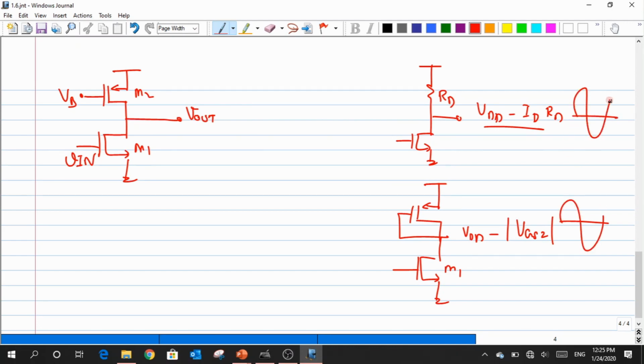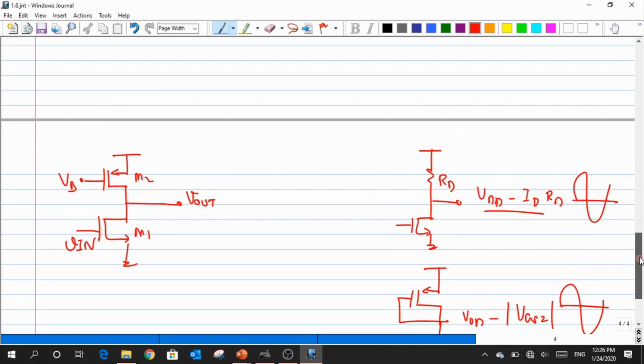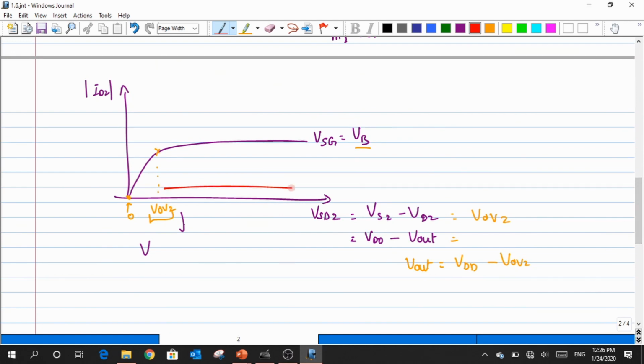That is all a different story. But in order to plot this, first of all I need to know what is the base value, the output Q point. Now the question is, what is my output Q point? Can you answer it? Is it VDD minus VSD2? I don't think so, because I'm in the saturation region for the entire segment. You see, over this entire segment, I'm in the saturation region. Any value of VDS, or VDS2, can fit over there. No, it is not VDD.